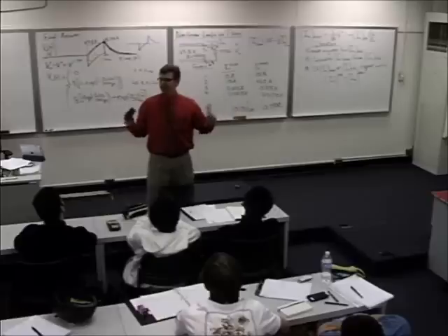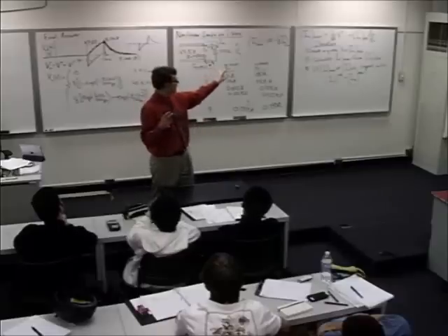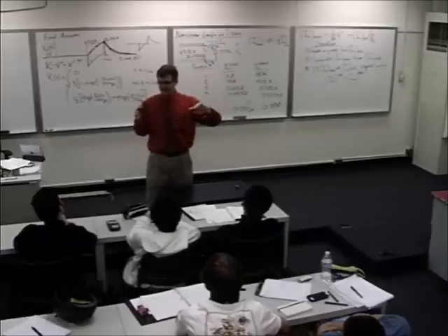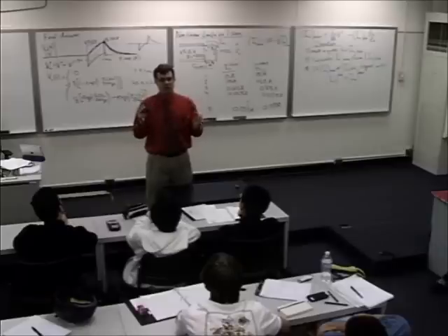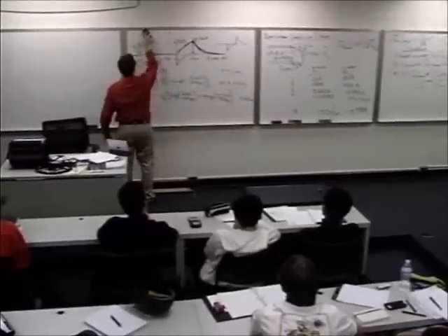And in that case, you've probably set it up in an unstable mode. And so a lot of times you can fix the problem by using this other formulation, which is just a rearranging and solving in terms of voltages.